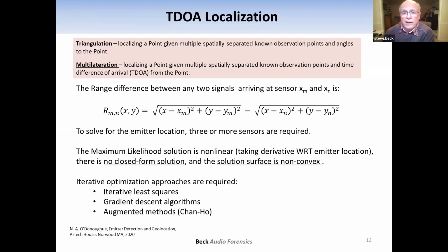Yeah, that's kind of what I think Shotspotter does. Okay, so they get these time differences of arrival to all of their sensors. They know where those sensors are. They compute these hyperbola for every sensor pair, and then they do some kind of iterative optimization to try and find the best intersecting point for all those hyperbola. So that right there, I think, is Shotspotter.